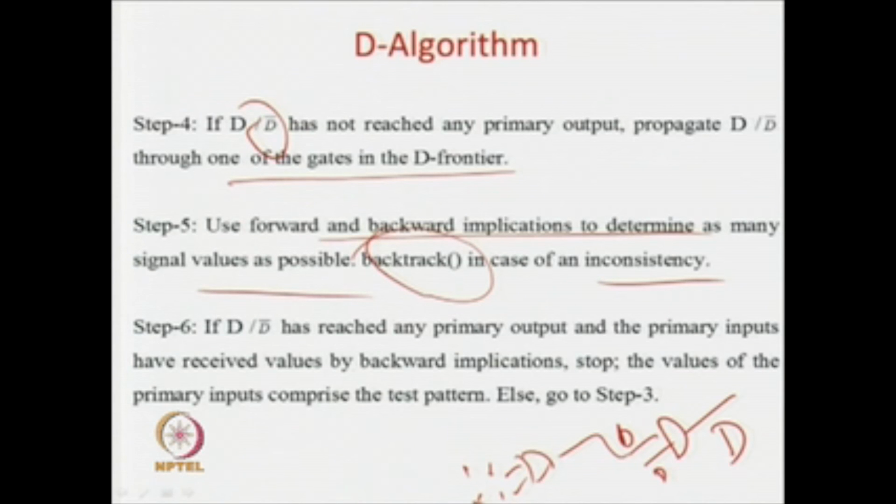Okay, in the last class we were discussing why you want to put x1 and not 1 1, or the other way around, that is, we always try x1 or 1x. Why not 1 1? Because 1 and a 1 in the OR gate, or x1 or 1x in the AND gate, the OR gate output is always a 1, which will satisfy your case, but you always use x1 or 1x, but not 1 1. So, we will see what the problem is if you are hard coding the signal values like 1 1, that is, if you are putting 1 1, then you are not using the concept of singular cover.